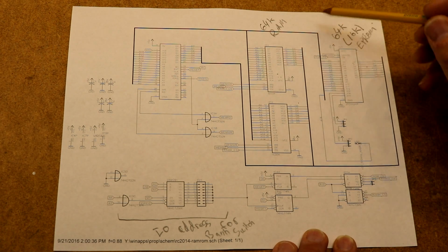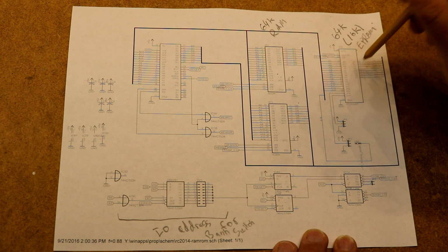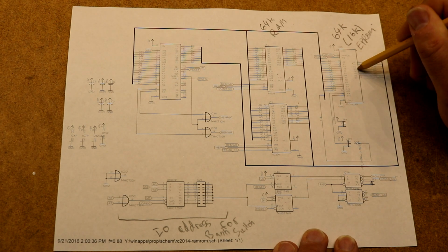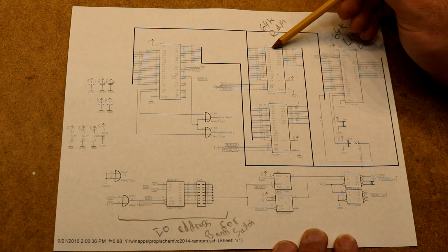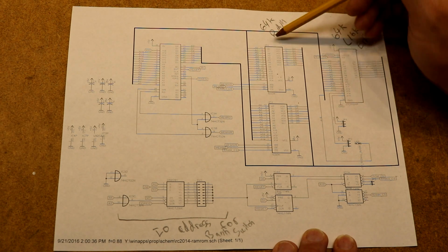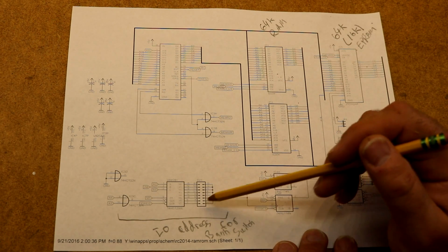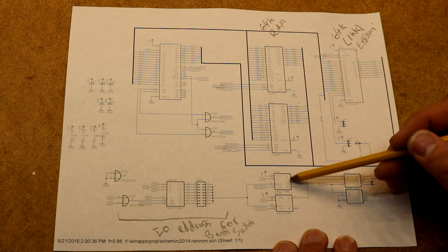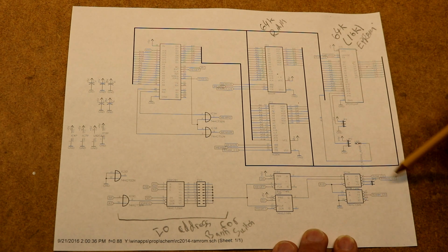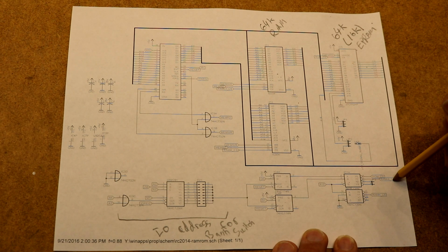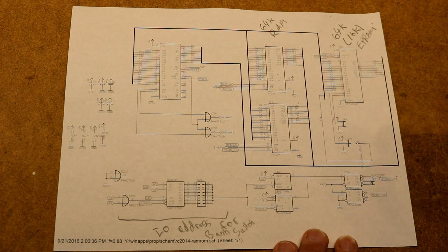The boot up logic is this. So you hit reset. Reset puts 0 in the flip-flop, which causes the EEPROM to be selected. The EEPROM runs the bootloader. The bootloader causes some stuff to be loaded into RAM. Then the bootloader is going to jump to the RAM program. The RAM program is then going to write a 1 to the I/O port that's associated with this jumper. That 1 will be stored in here in these two flip-flops, and that 1 will cause RAM low CS to be selected instead of the EEPROM CS. And that is our bank switching logic.